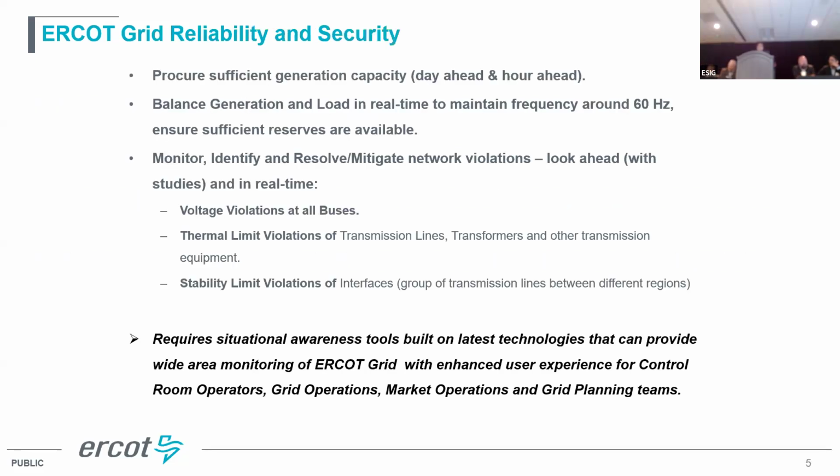With all of that, it becomes very, very complex to manage all the different components it takes to manage the reliability of the grid. That can translate to many different things: the frequency control aspect, power balance, congestion management, and the security of the system in terms of thermal violations and voltage violations.